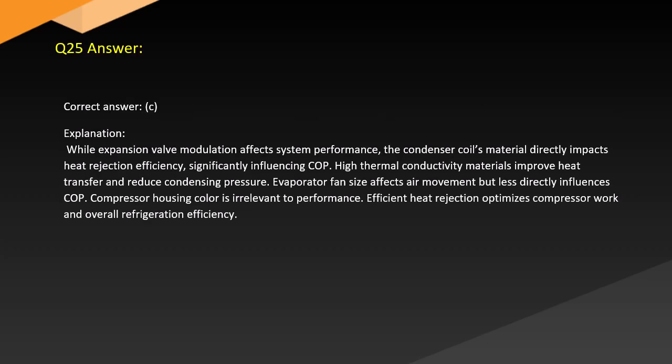Answer. Correct answer, C. Explanation. While expansion valve modulation affects system performance, the condenser coil's material directly impacts heat rejection efficiency, significantly influencing COP. High thermal conductivity materials improve heat transfer and reduce condensing pressure. Evaporator fan size affects air movement but less directly influences COP. Compressor housing color is irrelevant to performance. Efficient heat rejection reduces compressor work and improves overall refrigeration efficiency.